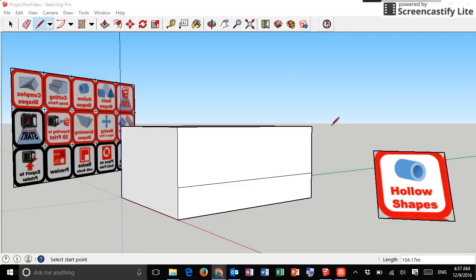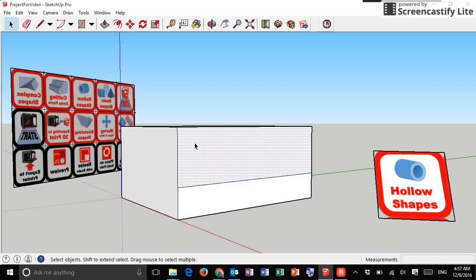As you continue building your shape in Google SketchUp, you may find you want to create a hollow space for things to sit. If you simply click and delete a side, that looks good enough, but if you look here, these edges are super thin, and thin edges or edges that don't line up and match up and touch exactly all the way across create gaps that your printer software won't know what to do with, so instead it will actually fill the whole thing in to make a solid brick, which is not what you're looking for.